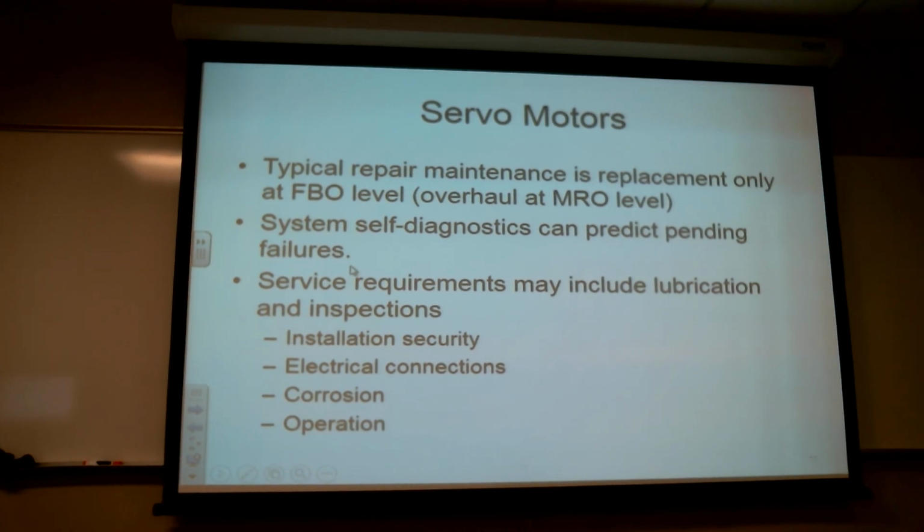So for you guys, it's electrical, right? What can go wrong? An open, a short, a failed power source, or any one of the above. There's not much else. If the programming's bad, the programming's bad. You're not going to fix that. Engineers got to fix it. So bad installation of wiring, connectors, corrosion, etc. Those are the kinds of things that are our realm.